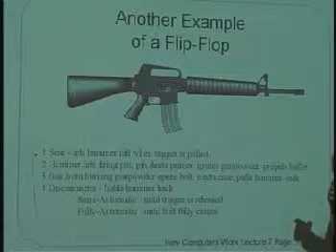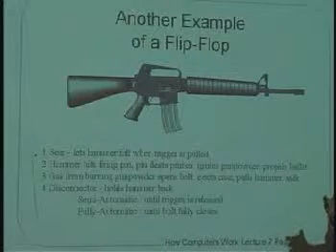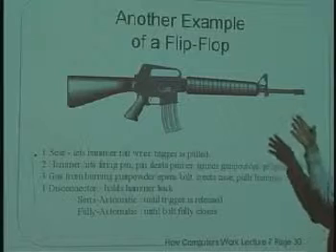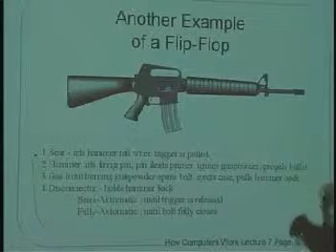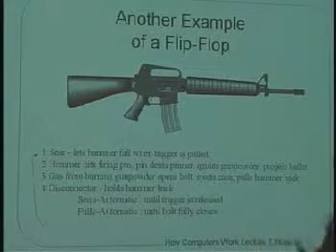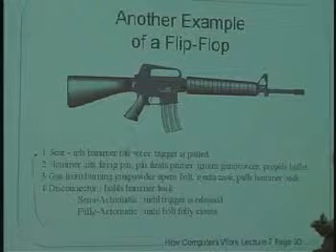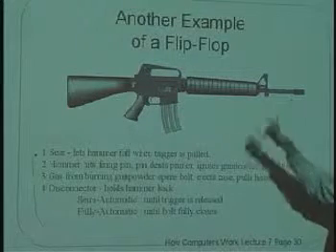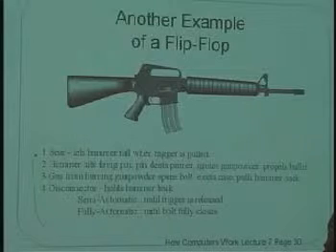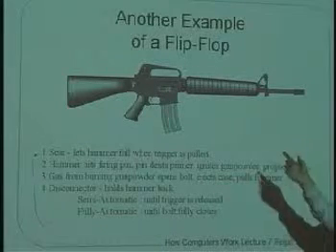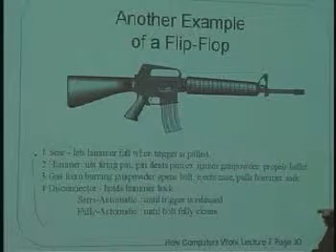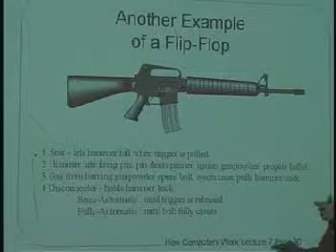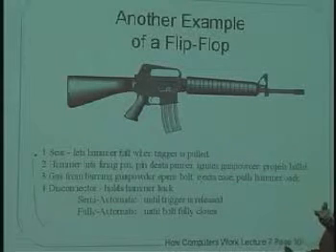If it weren't for the flip-flop in there, because it's a semi-automatic rifle, it has reloaded itself with the next round, and the trigger is still down. All this reloading of the next round happens so fast that your finger, if you're firing one of these things, has not yet lifted off of the trigger. So the question is, what stops the next bullet from coming out?